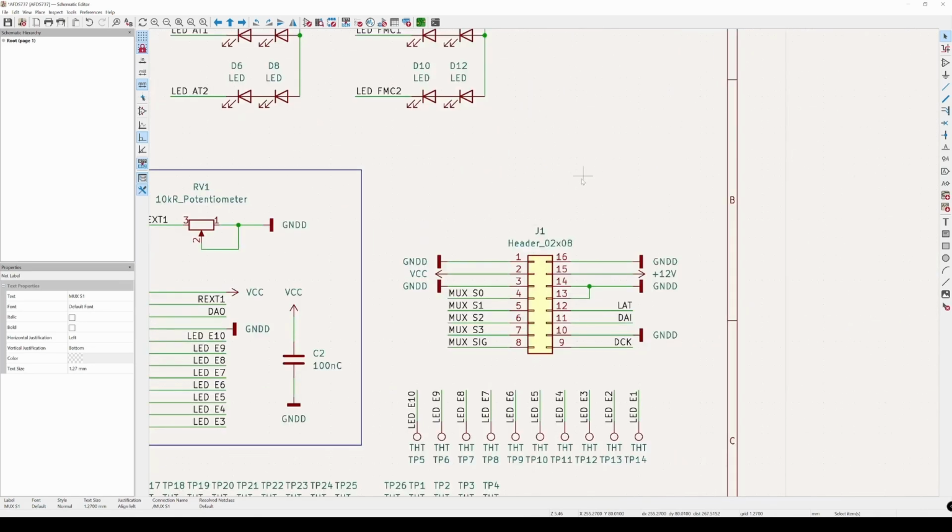And then, since I'm using a 2x8 connector, since that's what we have, I was left with a few empty pins, and I decided to fill those with ground, so we can have some extra grounds coming in. You can see we have a total of 6 ground pins in between all of these. One ground is connected like so, so we didn't need to add the symbol in the signal separately.